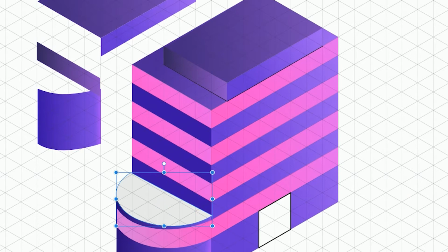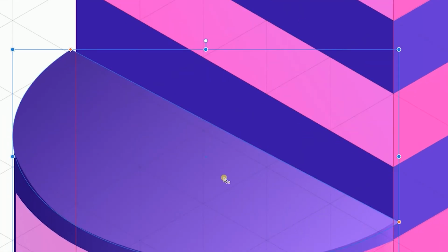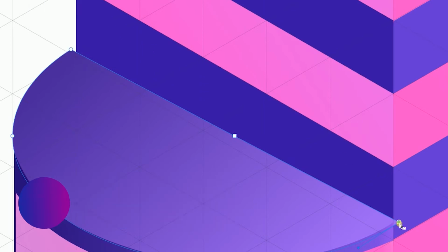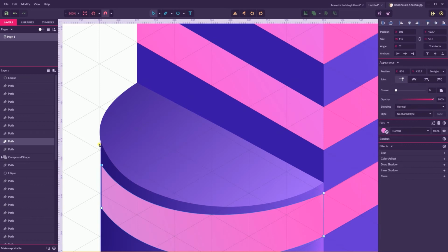Let's also recolor this roof. I believe we can rub the color from this roof and then darken it with a shadow. So let us start with the linear gradient again, and then color. And last but not least, of course, as you can see, I have these small tails, so I need just a little bit to resize the whole shape, yes? And I will darken this part as well. So let me grab the Subselect tool and then convert it to the path. Ctrl-Shift-P, Command-Shift-P. This is how you can convert it to the path. And also I can unsnap from the grid, or I need to hold Control to do the same temporarily.